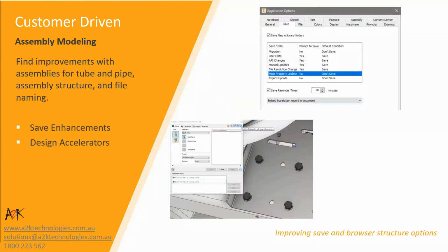So the application save tab enhancements, you can see in that image at the top there, using the new controls to set the behavior for Inventor to prompt when saving. The save state prompts replace the prompt to save the recomputable updates, the prompt to save for migration, and the do not list reference files that defaults to no in the options file.